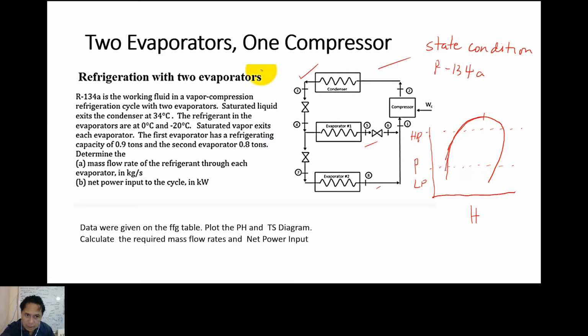So here, I'm going to repeat because this is the basic. In the board exam, it is always given. The left half is saturated liquid, meaning 100% liquid. The right half is saturated vapor. That's why here the subscripts are g. G means gas, for example hg, enthalpy of gas. Here, hf is enthalpy of fluid, which is liquid.